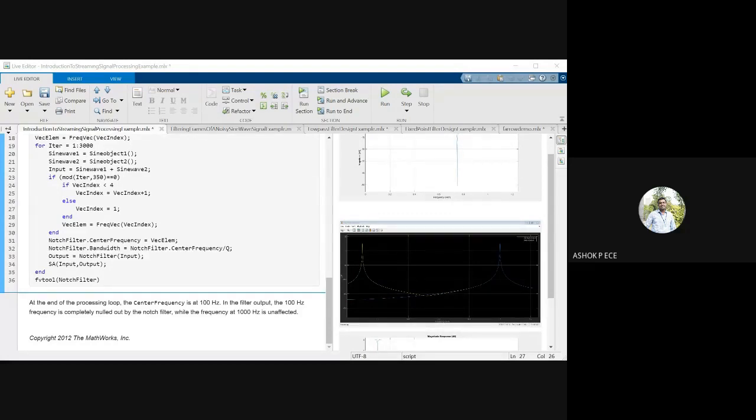And finally, CCDF. You have the probability measurements. All the probability measurements you have. For CCDF measurements, we need this many samples, but we have not got that many samples. So it is saying it is not able to display that particular thing. Okay, so that is the thing using the spectrum analyzer.